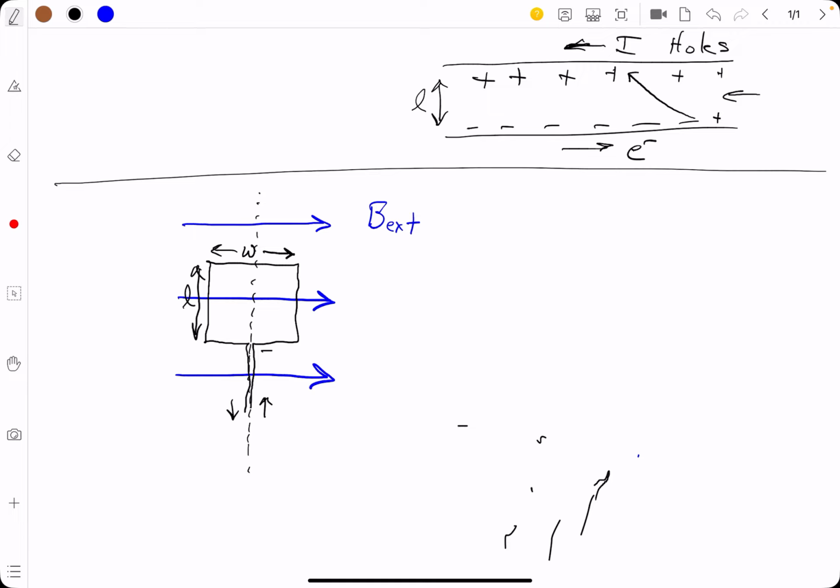the bottom part. These sections right here, when that current is going through those sections, it is not perpendicular to the B field. It's parallel with the B field. So it's not going to allow us to create a force. Now, if it happens to be rotating about its axis and it is perpendicular to the field, the current going in the top section and the current going in the bottom section cancel out, because one's going one direction, one's going the other, but the B field stays the same.